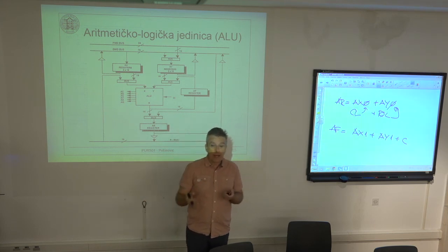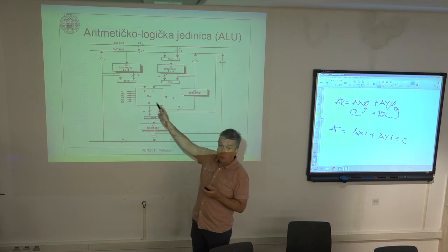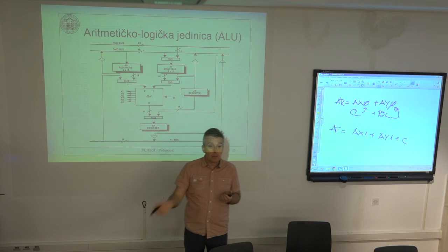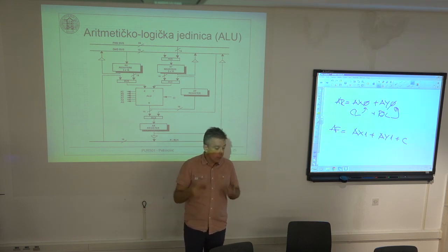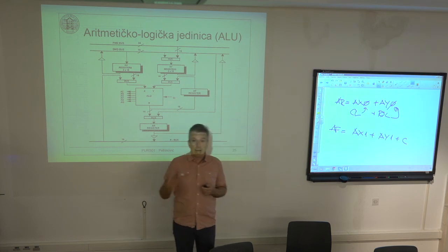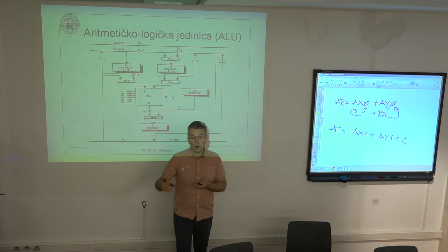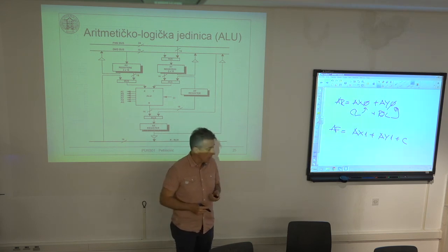So as soon as I enter the interrupt service request routine, I simply switch the registers from white to black. I use the black register. And at the end of the routine, I simply switch back from black to white. In this way, I'm saving a lot of cycles that are normally used to do this context save and context restore when servicing the interrupt.